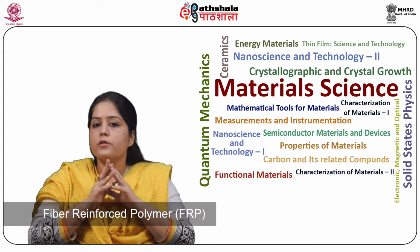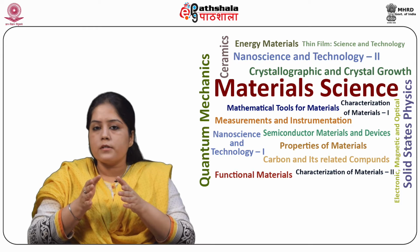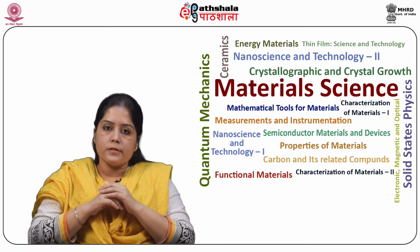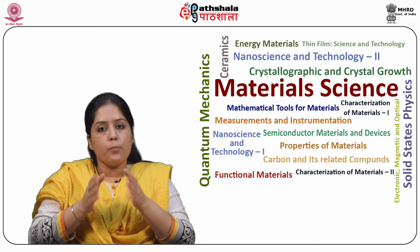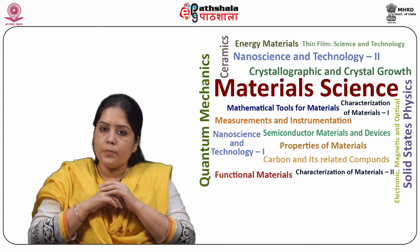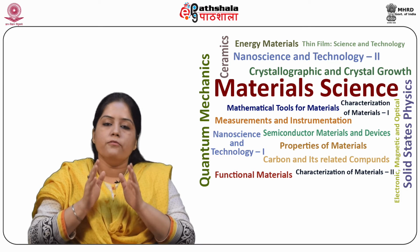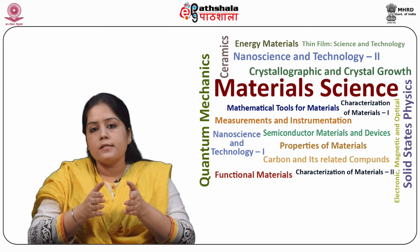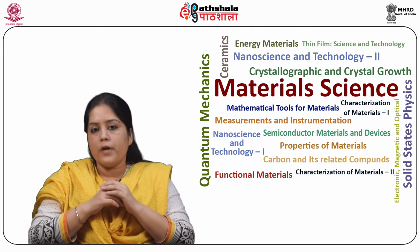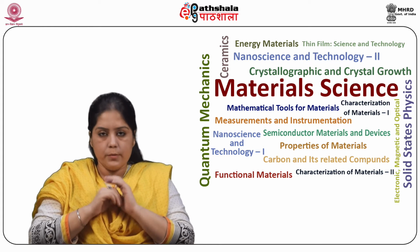Fiber reinforced polymer is usually made of a polymer matrix reinforced by short or continuous fibers. The polymer matrix usually consists of epoxy, vinyl ester or polyester thermosetting plastics because of their excellent properties and the cost of the material. Glass, cellulose, aramid, silicon carbide and carbon fibers are commonly used in fiber reinforced polymers.